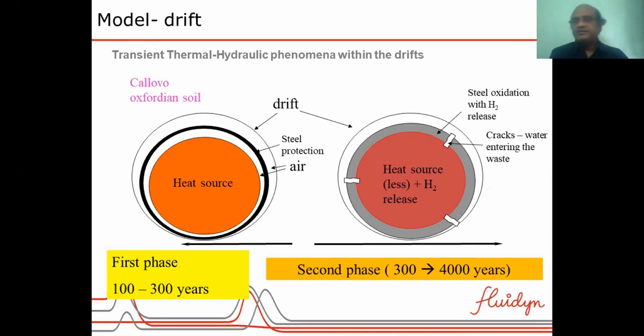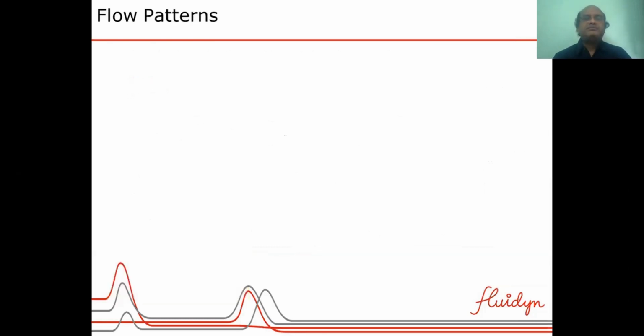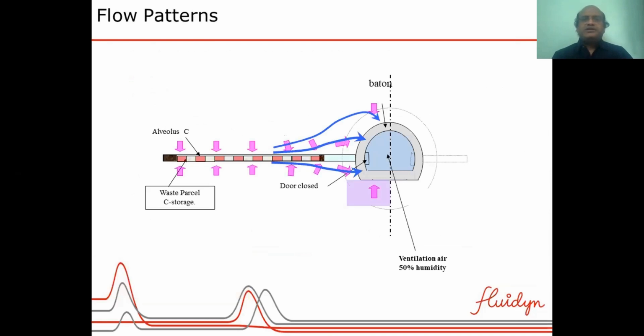The pressure can increase inside due to the hydrogen production and the heat release, and this hydrogen can get into the soil, which can again increase the pressure there. All these processes are modeled. This involves flows in unsaturated soils. It flows through porous media, and it is a two-phase flow, so the capillary action has to be considered.